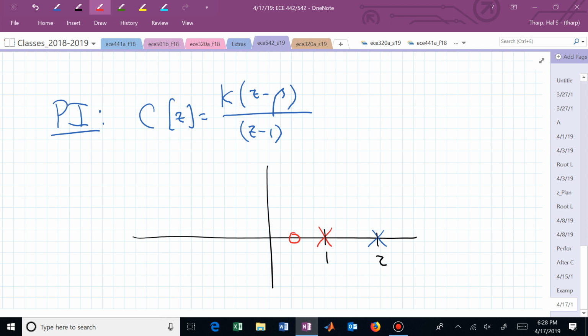Make sure this 1 minus T of Z expression evaluated at the unstable pole is satisfied by your T sub C of Z expression, so you don't cancel an unstable pole. So hopefully Ragazzini has taught us we can't eliminate unstable poles and zeros that way, but we can encourage them to come inside the unit circle